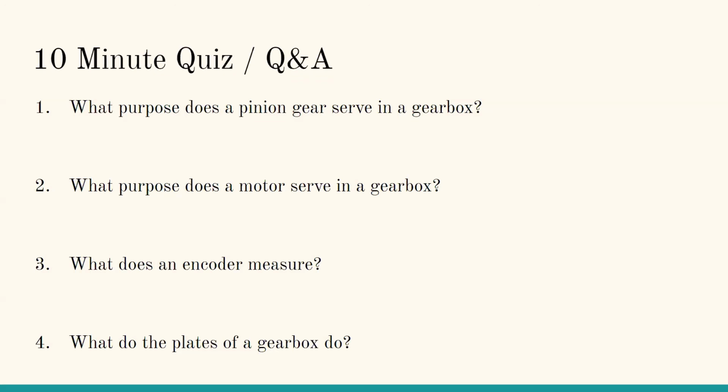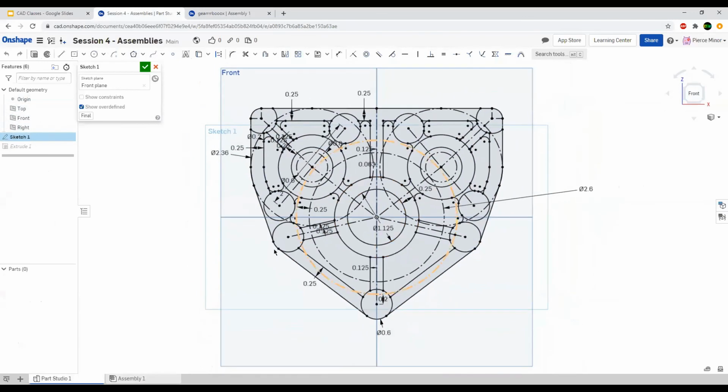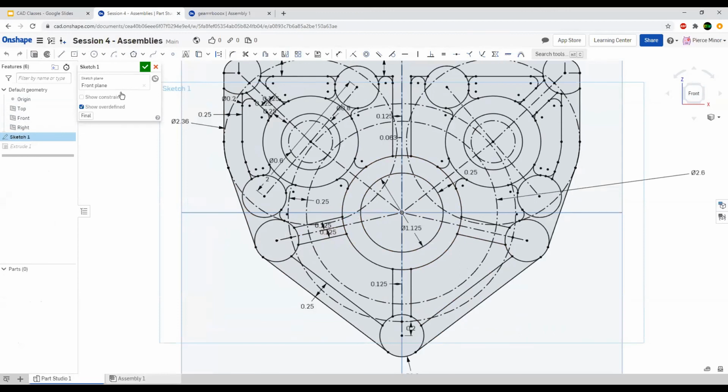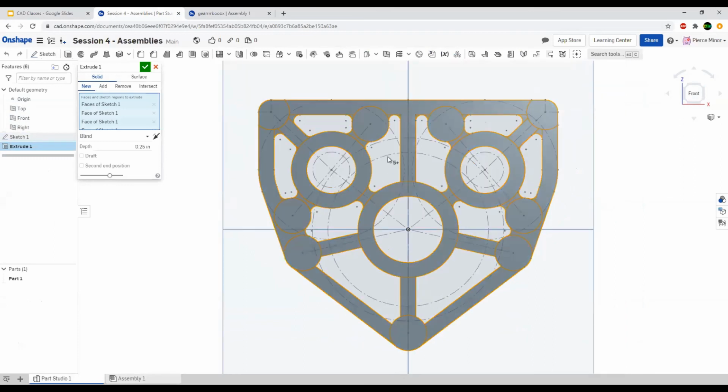Your extrusion won't register the struts. It is only doing the whole gear. So it sounds like you're talking about, let's go back to extrude. What parts is it only doing the whole gear? Do you mean like this big circle in here? Yeah, okay. First of all, is it a construction circle? Because it should be.